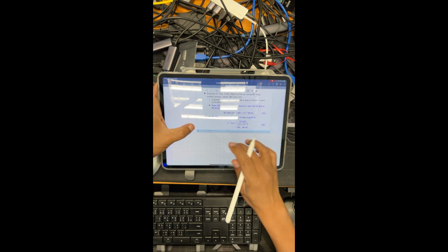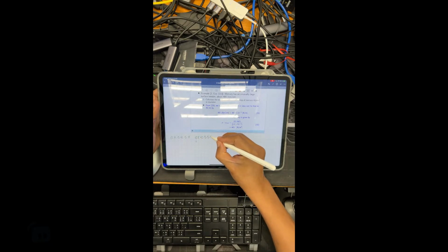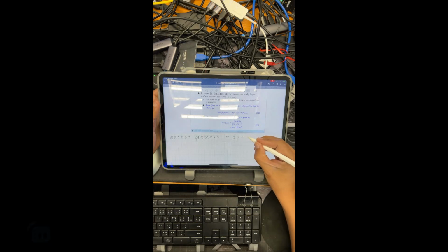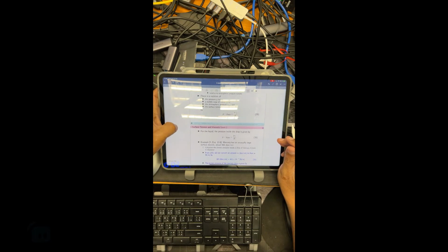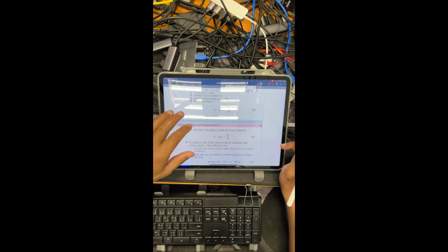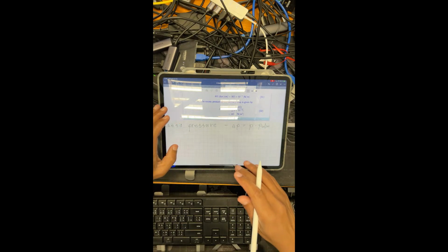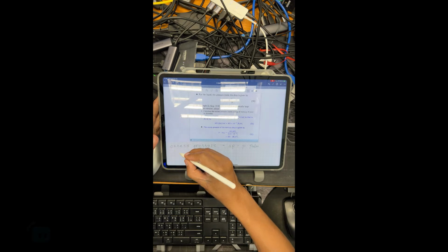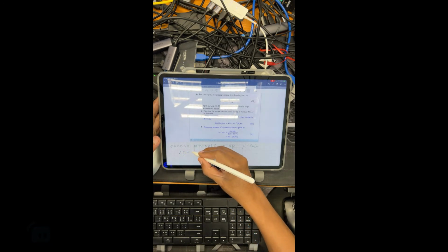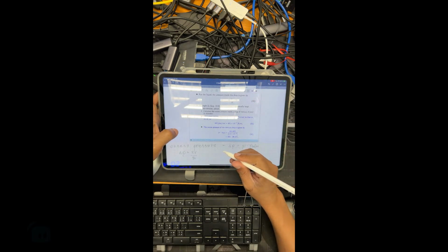Yeah, they asked us about excess pressure, which is delta P, and it's equal to P inside minus P ATM, right? According to equation 30, it's 2 gamma divided by R, right? This is the liquid drop, and for the bubble we have to use a different one. The formula we are going to use is delta P equals 2 gamma by R, and what we need to find is the following.